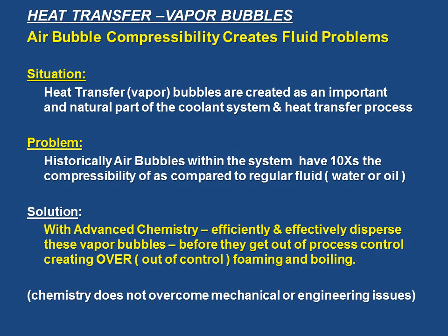One of the things we have to look at is that air bubble compressibility creates fluid problems. Here's the situation. When we're trying to have heat transfer, vapor bubbles are created as an important and natural part of the coolant system and heat transfer process. The problem is that historically air bubbles within the system have 10 times the compressibility as compared to the fluid. Now this applies whether it's water or oil.